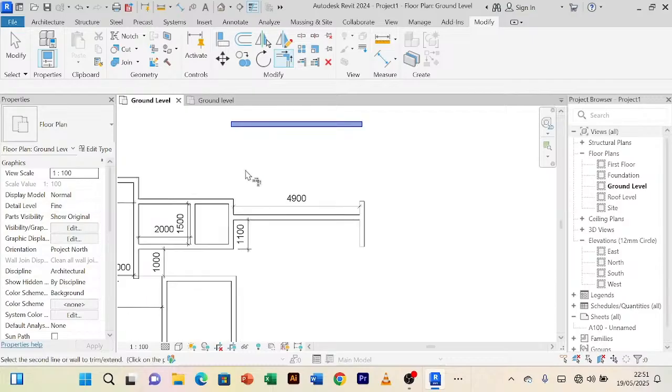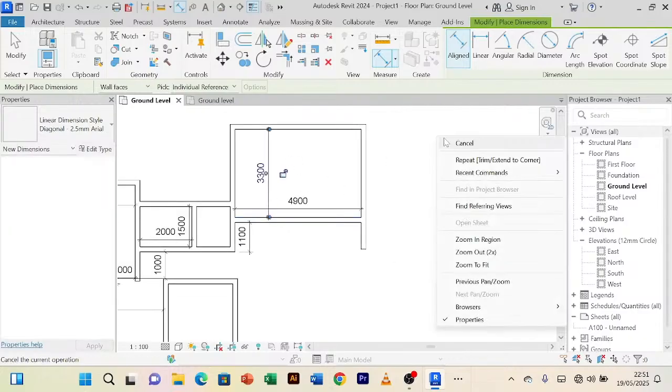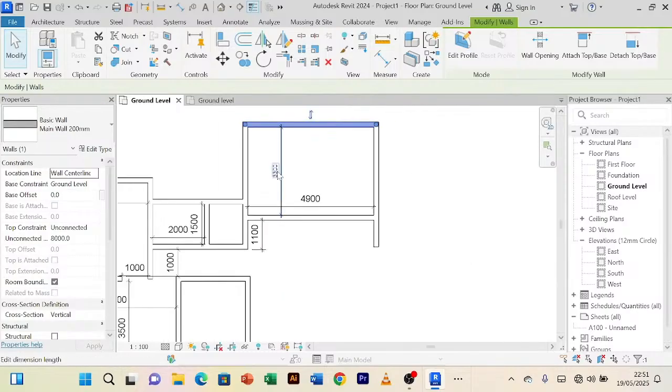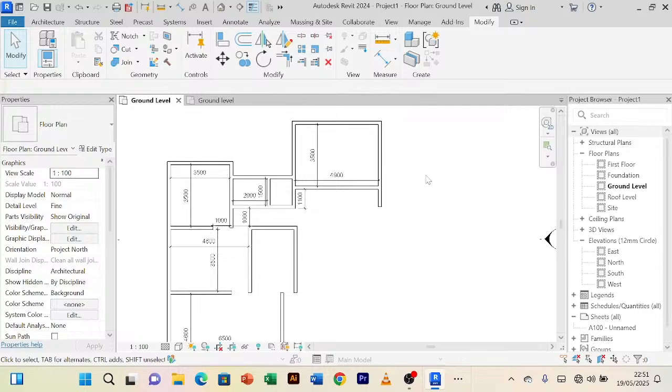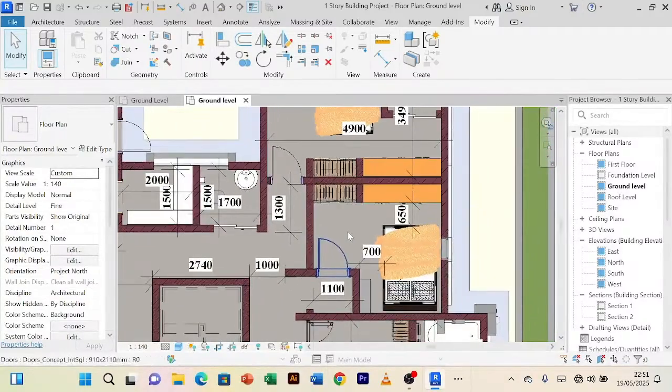You click on it, you click on this wall, connect it here, you click on this, you connect it here. Then you can bring your measurement tool, you measure this, you measure this. So you remove the wall thickness. So you have to give it 3.5. Yeah, now there. I think we have created this bedroom, that first bedroom.